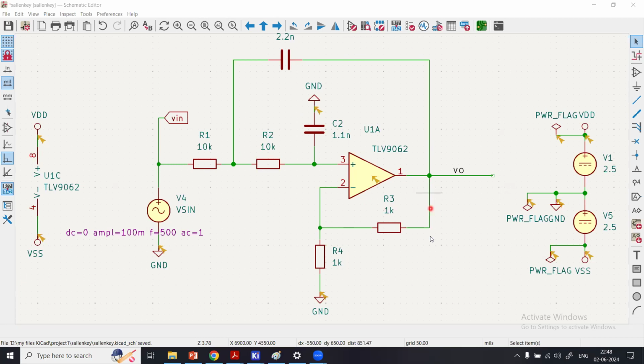And if we short this resistor R3 and open circuit or remove this resistor R4, this amplifier takes the form of a voltage follower circuit, with a feedback directly connecting the output back to the negative pin of the input. So we also covered that. In that case, the op-amp circuit behaved as a buffer between the output and the input signal. So here is an input signal, and finally here comes the voltage that becomes an input to the positive pin of the op-amp.